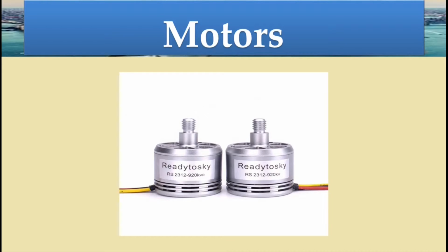To drive these motors, we need a driver that is called ESC, Electronic Speed Controller. Its input you can take from the drone power plate, and on input it has 2 wires and on output it has 3 wires, as BLDC motors have 3 wires input. You also need to provide PWM signal on the input of the ESC, and these ESC will also provide power supply to our controllers and take PWM signal from the controller. It is your choice. You can also use external power supply as well as ESC power supply.